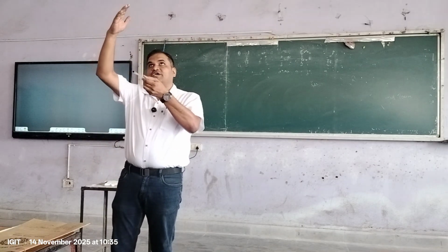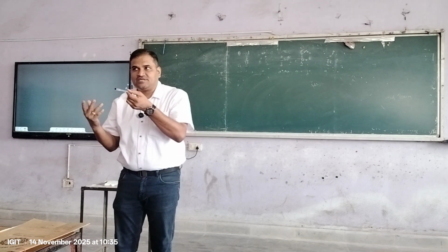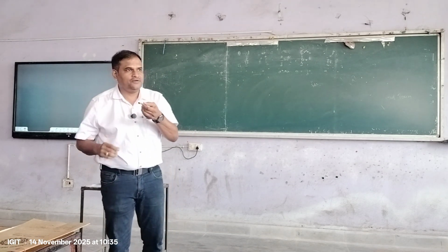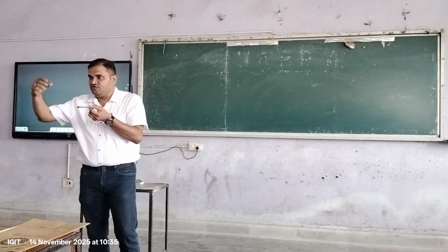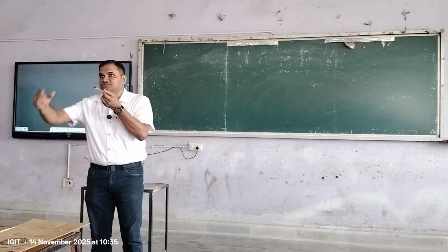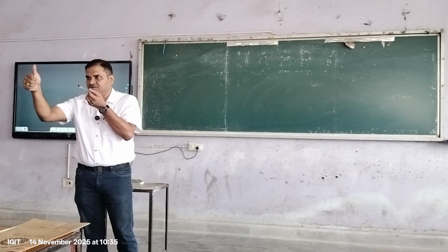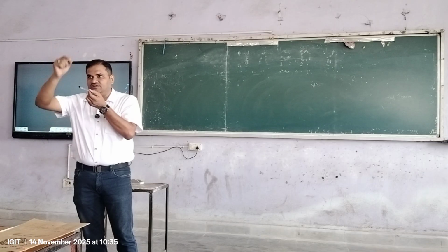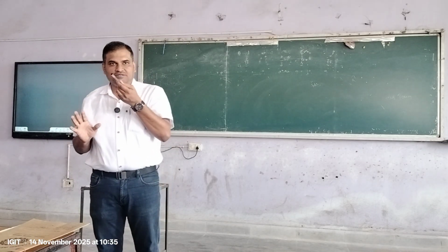मैं आपको बोला कि फ्लक्स ऊपर से नीचे की तरफ आ रहा है, करेक्ट? ये फ्लक्स कहां से कैसे जनरेट करोगे बेटा? How can you generate the flux? If you keep the north pole on the top and south pole at the bottom, so the flux will come from the north and enter into the south. Perfect? Okay, if there is a constant flux, it will get a constant torque. Correct? It will get a torque like this.